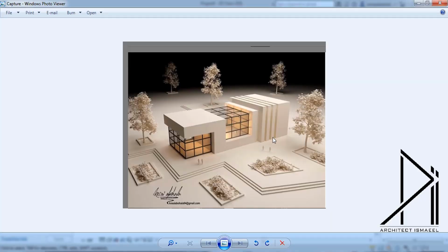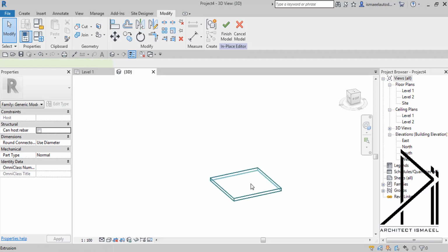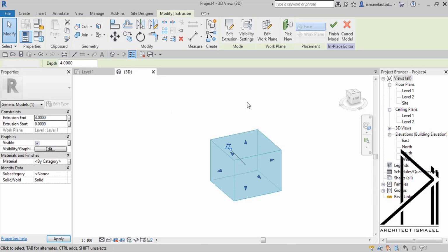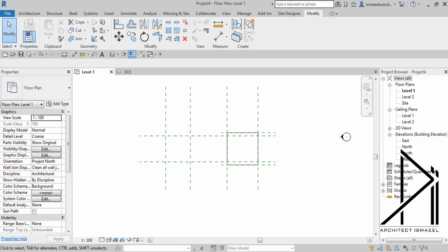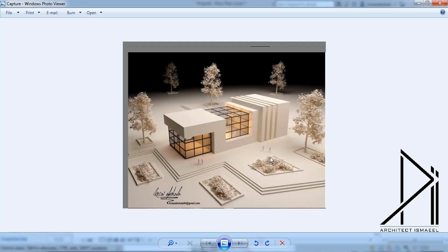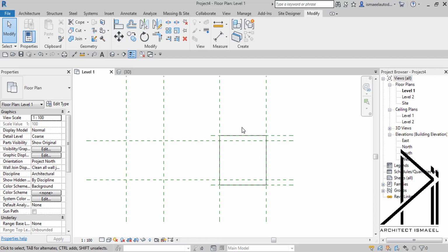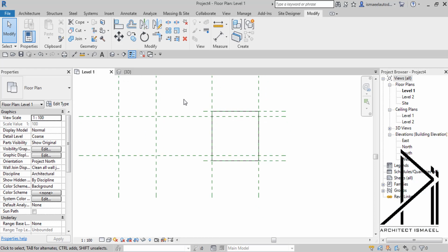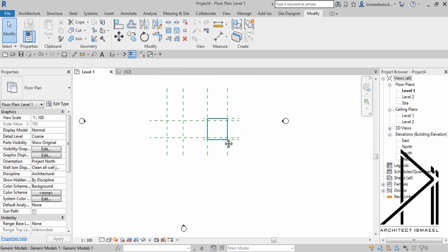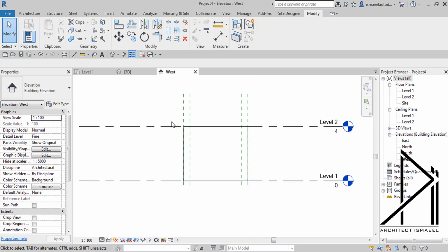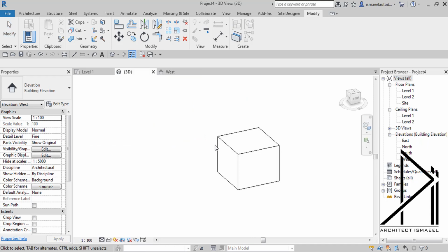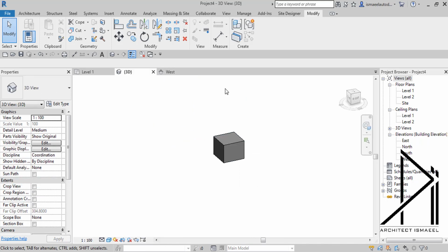Let me see the elevation or the height of it. I will consider it maybe 4, let's say. Okay, let me just say OK now. Now I will use a sweep maybe just to create these voids, or I could make another extrusion and even put it as a void form. But because we just used the extrusion, I will use the sweep maybe. So I open that elevation. If I go to 3D, now I'm facing this one. SD is the shortcut to go to shaded.